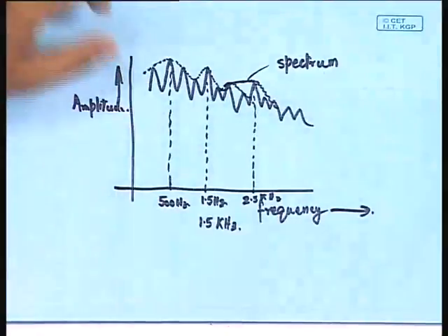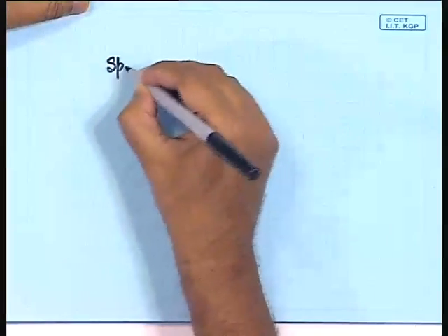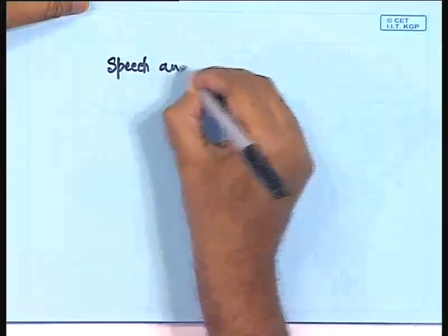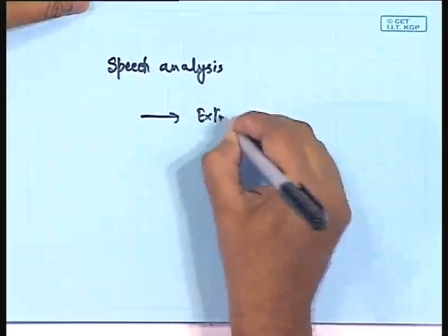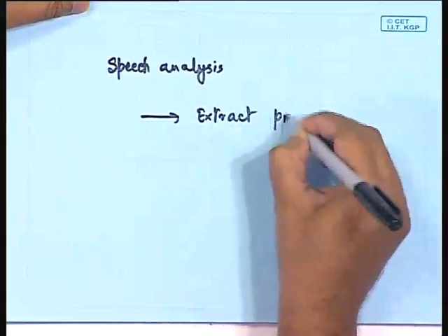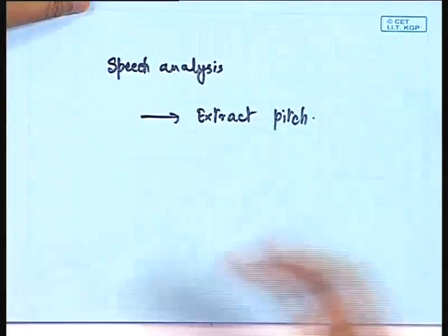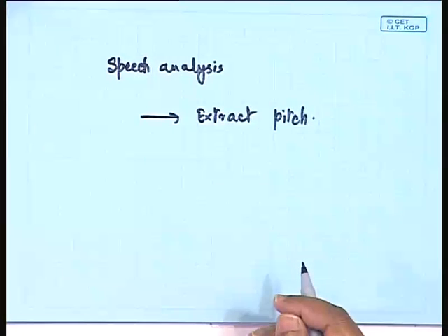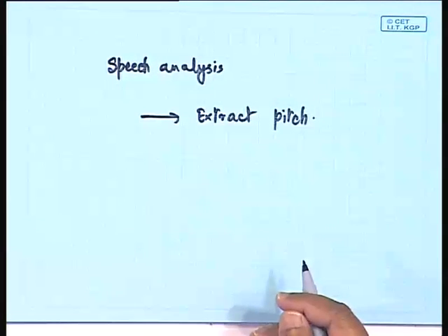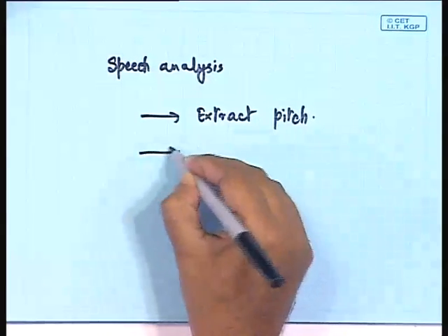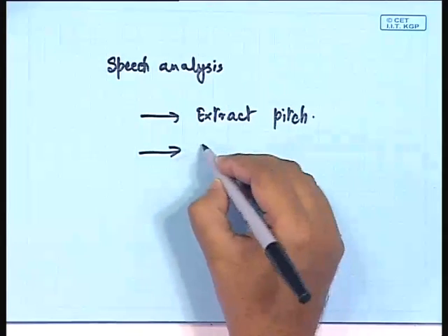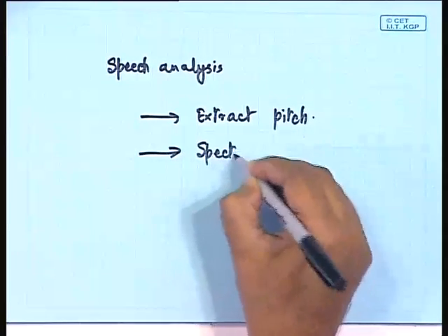We definitely have to do a speech analysis, and the purpose of the speech analysis should be that we first of all extract the pitch. If we are able to extract the pitch, then we will also know when the pitch varies, because extraction of pitch would be from our speech signal itself. And then we should also do a kind of spectral analysis.